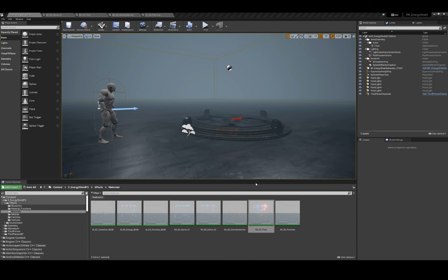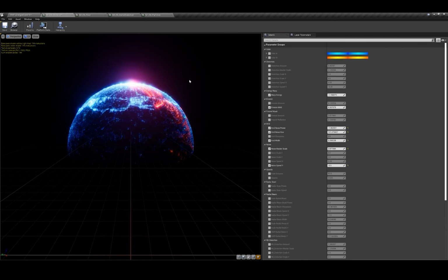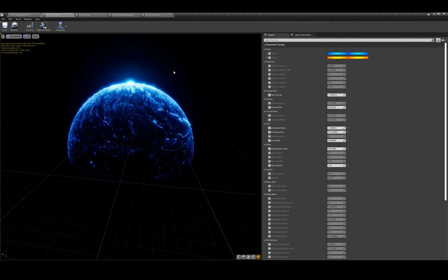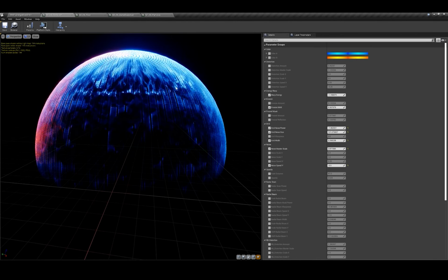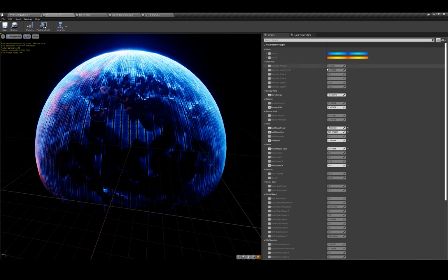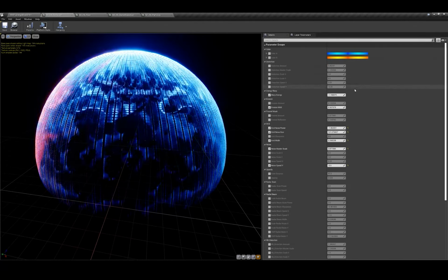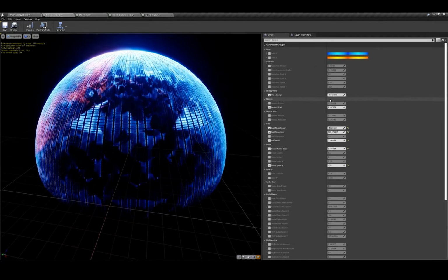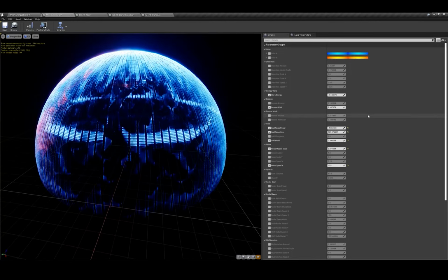In our material instances, we'll start off with the dome. In the examples or in the master project, you'll see 2. I'm going to use dome 2. I just had different variations going on, I think, with the grid lines. Just make sure this is real time here so you can see it. So the values I changed here are the warp energy and the erosion.